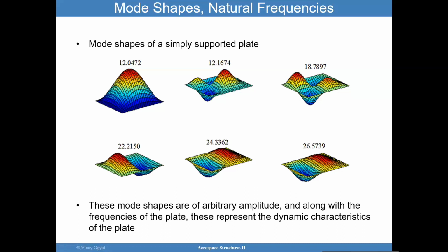Note that when you get a mode shape, when you do a mode shape extraction procedure, the amplitudes tend to be arbitrary. I'll explain why that is, and it has to do with the fact that this is an eigenvalue problem.